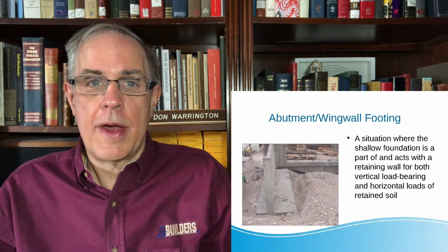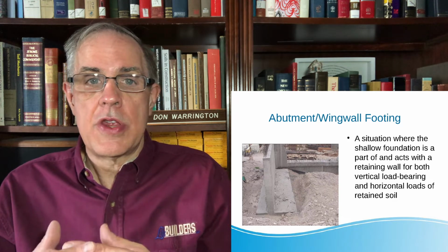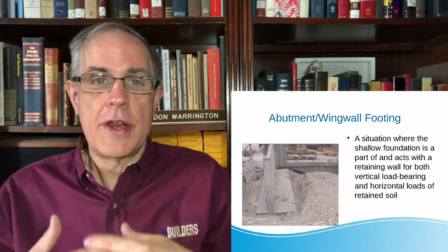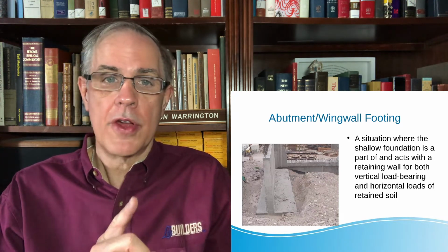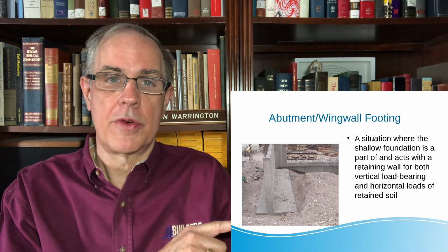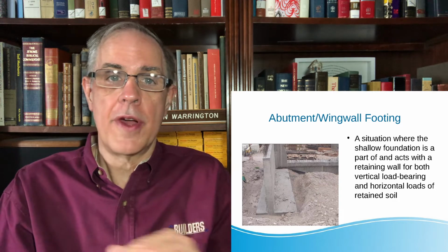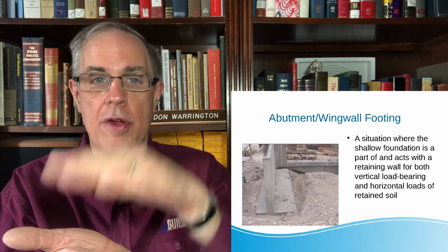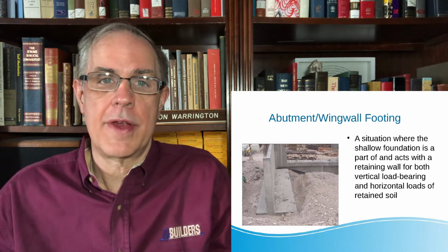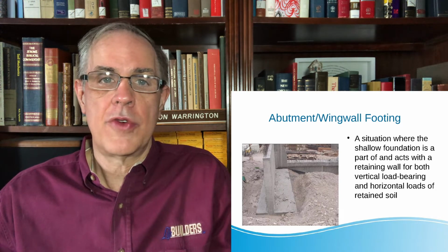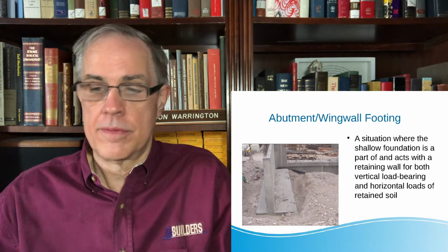When we get to lateral earth pressures, we're going to talk about the use of retaining walls to resist lateral pressures. But also for this type of thing, which is a cantilever wall, the wall is also a foundation. In other words, it supports loads this way and also resists sliding loads this way. And we'll get to that when we get to cantilever walls, but this is a situation where the retaining walls and the shallow foundations come together.